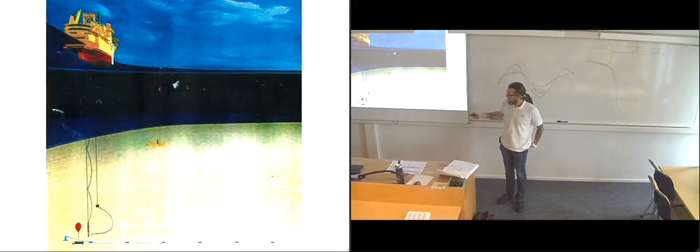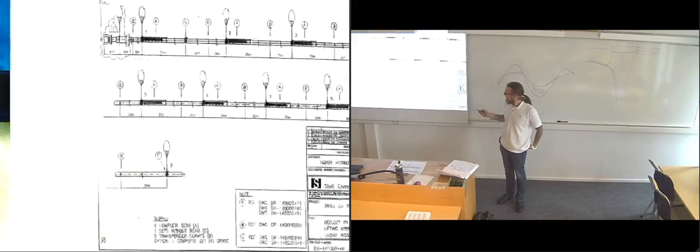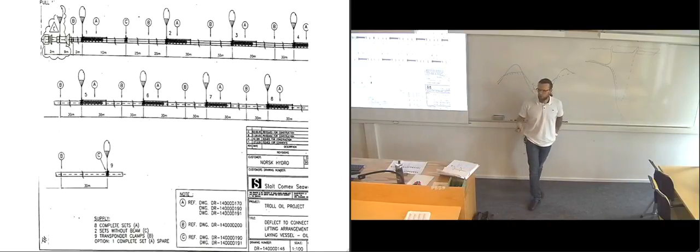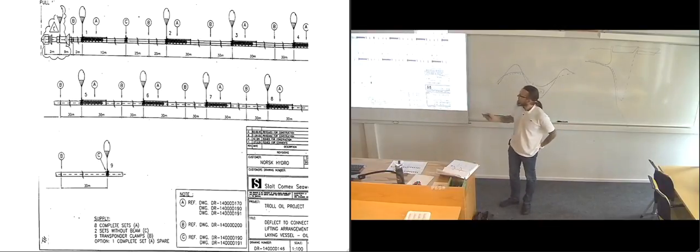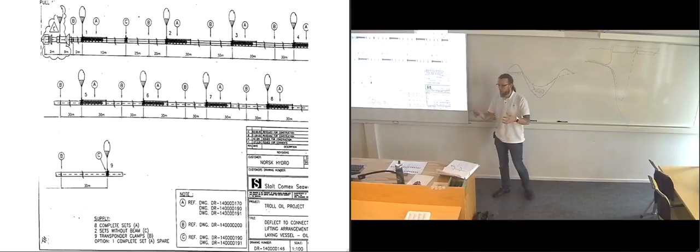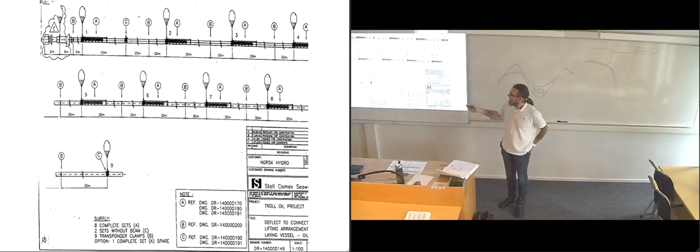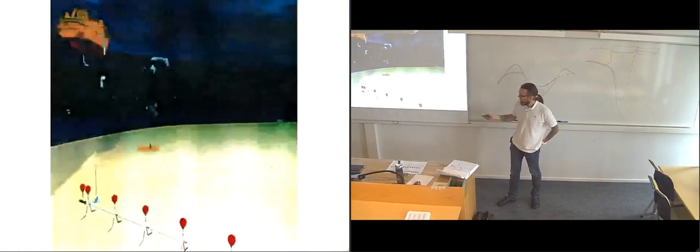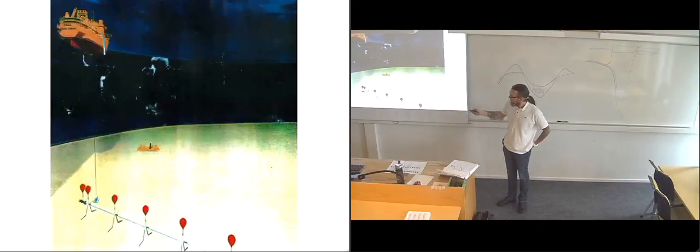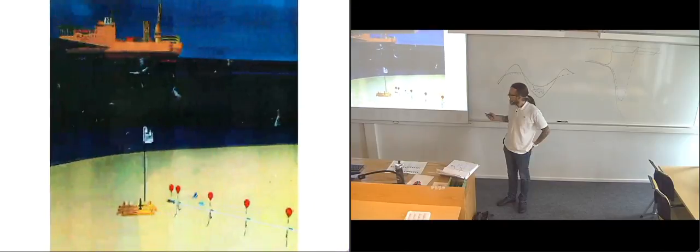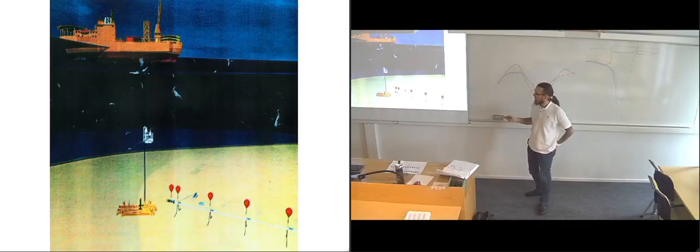So they have the ship that puts down balloons, actually, just like we saw on the clip. They also used balloons to make the pipeline lighter, and they do calculations beforehand because they know how much gas they're going to fill into each balloon, so that they know how buoyant it's going to become, and then they can calculate the length between each balloon. So they put the balloons on, and the ship starts pulling it, and it pulls it until it's close by the connection structure.